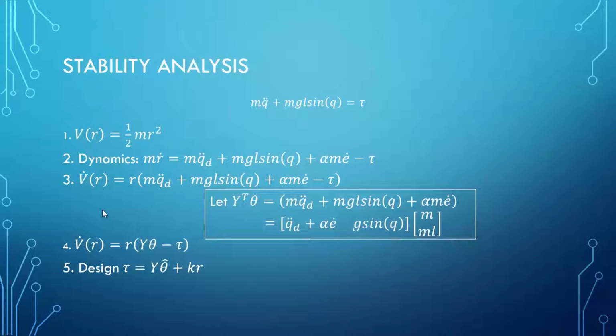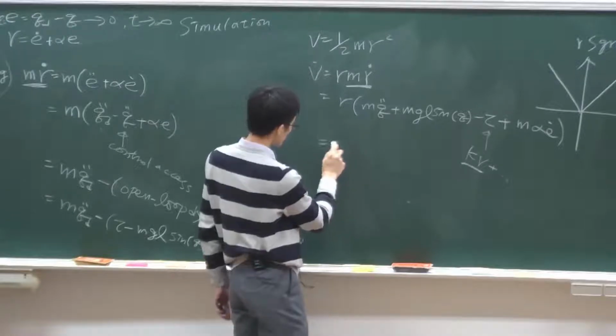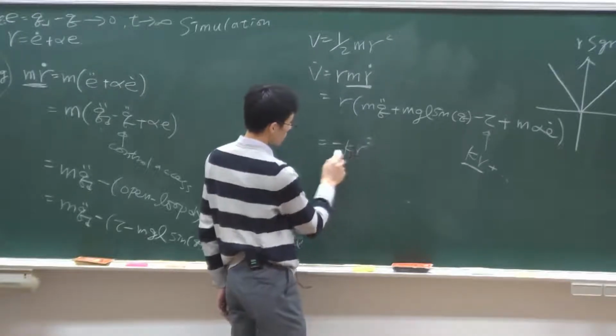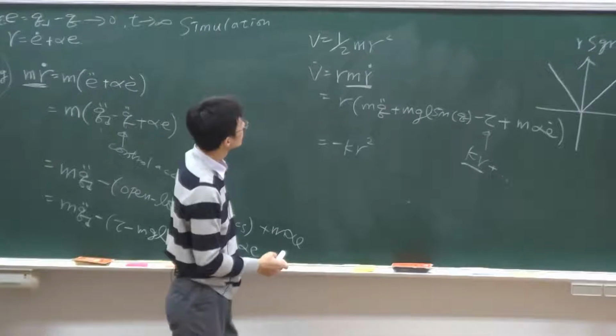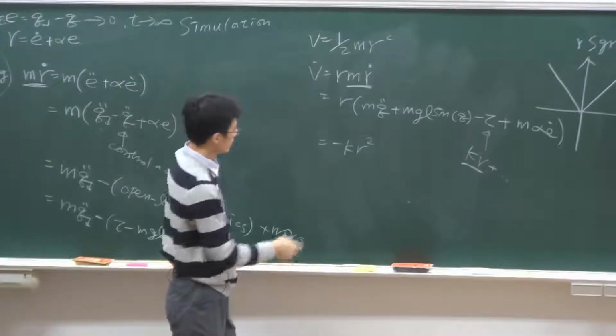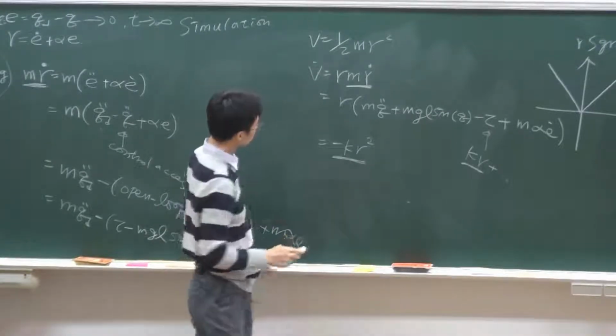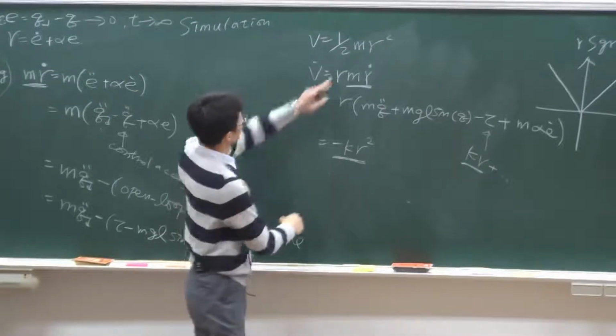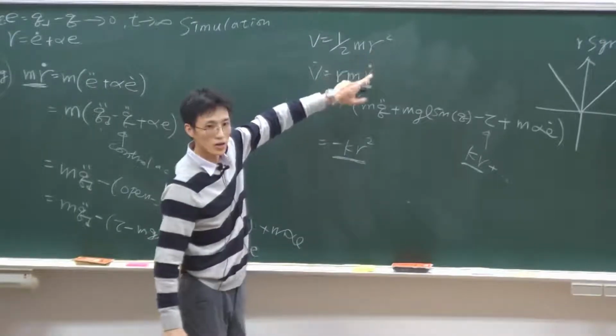And that's because we are using adaptive control, okay? Here we have feedback control terms, and this term has different functionalities. This KR term times the R term here can create some good terms, which is minus KR squared, right? And that's essential to make V dot negative definite, because V is a function of R, okay?